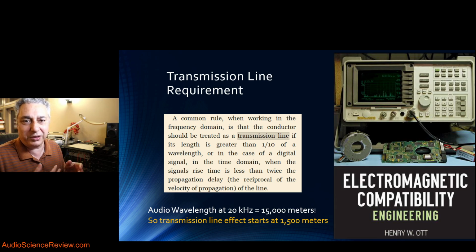That's why the phone company in the old days, when we used wired phone lines, going from city to city, yes, you worry about transmission line effects even for voice transmission. But in our world with a 1 meter interconnect cable, we're 1,500 times below where this effect even starts to become significant. So any talk about transmission line effects for audio cables, interconnect cables, or any kind of audio cable, makes zero sense. It's immediately a red flag saying whoever is saying this doesn't have a foggiest notion of what they're talking about. Go talk to any RF engineers, any serious engineer, they'll tell you this. They'll laugh at you when you say an audio cable is a transmission line.